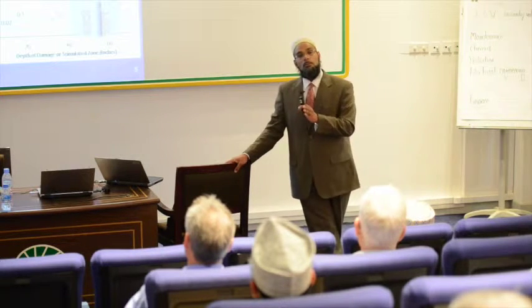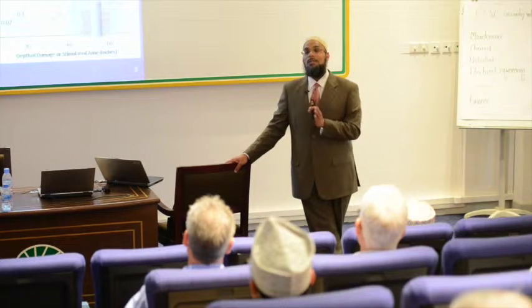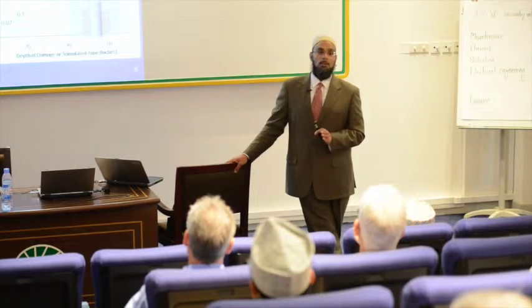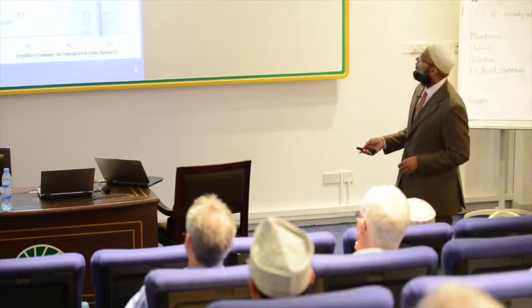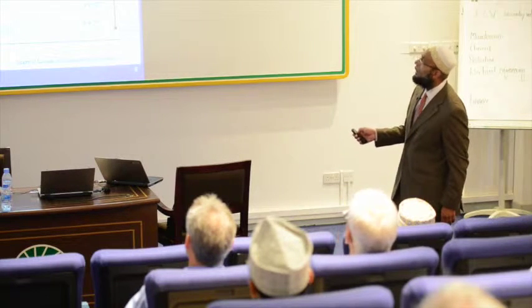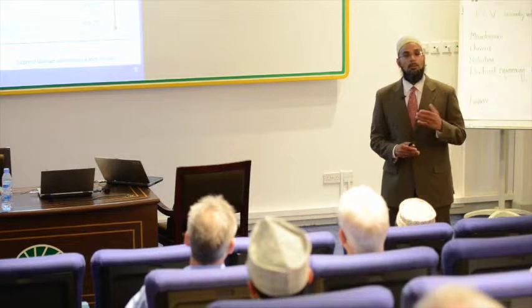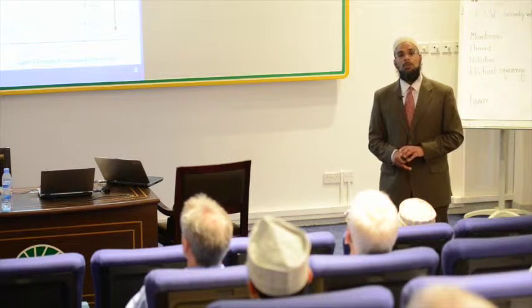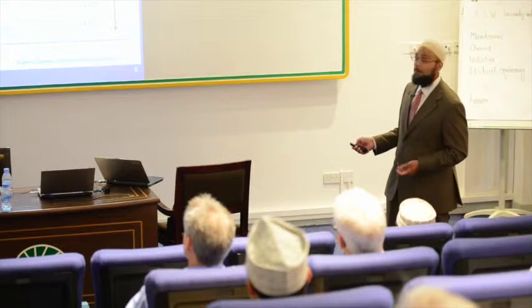Now people who were thinking it was maybe a failure, technically it was a failure, because the well is supposed to produce 6,000 barrels of oil per day, because the skin that we normally get after carbonate stimulation is -2, -3. So the first stimulation treatment did not change the skin.